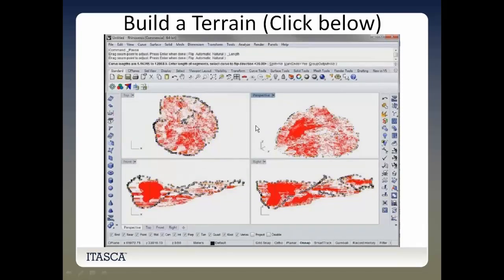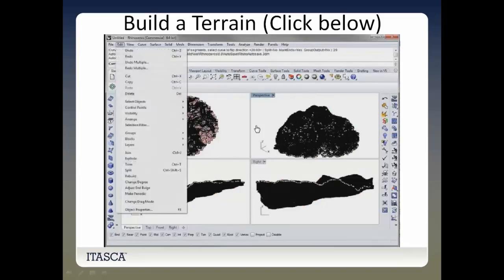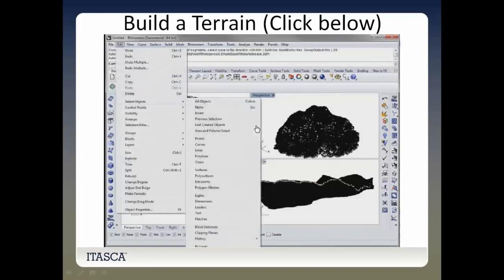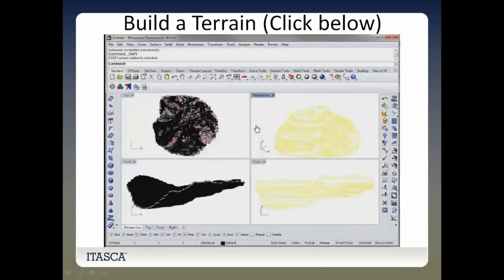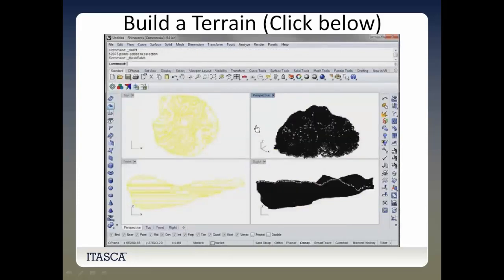Basically, I'm breaking these contour lines into, say, 10-meter chunks. If these contours are away from each other, say with a Z separation of 10 meters, I split these contours into 5-meter chunks, and I just extract the points that result from that. This is the points extracted from these contours.